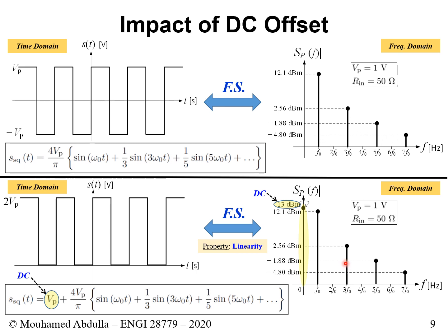You cannot use this equation for the DC component. It will not work. The key reason why it will not work is that that equation has an RMS; we determine the RMS value. In the DC component, you do not need to find the RMS value. In fact, the RMS value and the actual value here will be the same. So you cannot use that equation, and doing a V peak divided by the square root of 2 would not work here. You do not need to do that. It is already in DC form, so you do not need to find its RMS value.